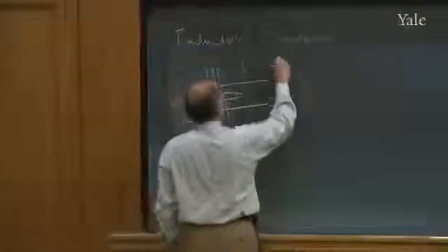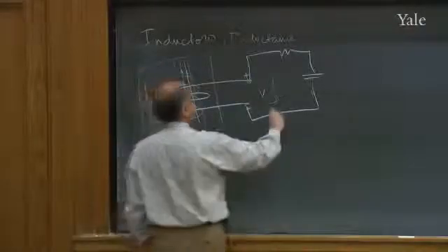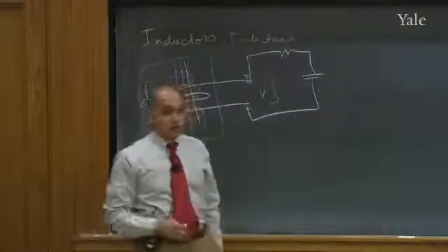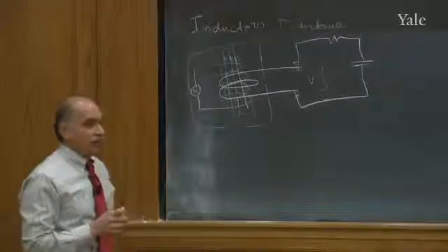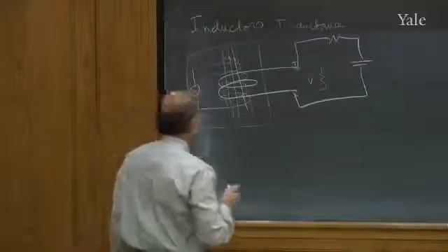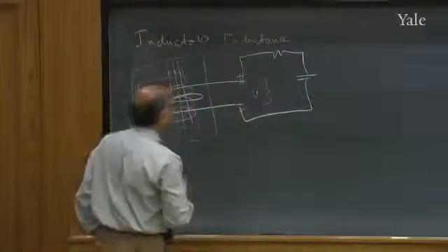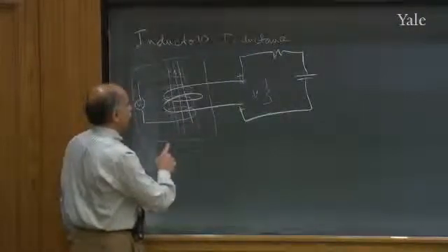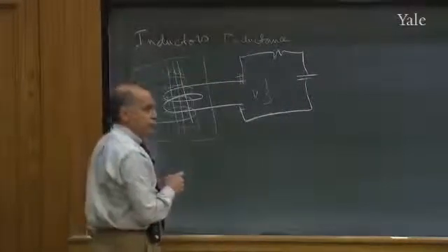We are going to take such things and put them in electrical circuits and so on. We'll draw all kinds of circuits later on. And what I will do in all those calculations, I will say I start here, I go around a loop, and I come back, and the change in voltage should be 0. I'm going to use that principle. But there is one flaw if you don't think about it, that says maybe I shouldn't do that. You remember that you can define a voltage only for a conservative force, whereas you definitely have non-conservative forces that work in this problem. That's why they have a line integral not equal to 0, and yet we apply the laws of conservative forces or a notion of a voltage in a circuit. So I want to explain why that's allowed.